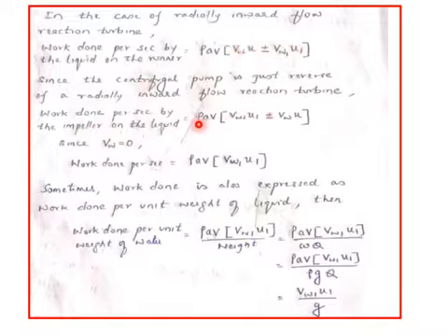So therefore we can write it as rho AB into (VW1 U1 plus or minus VW U). We know that VW is equal to 0 because here beta is 90 degrees. So therefore the formula becomes: work done per second is rho AB into VW1 U1.